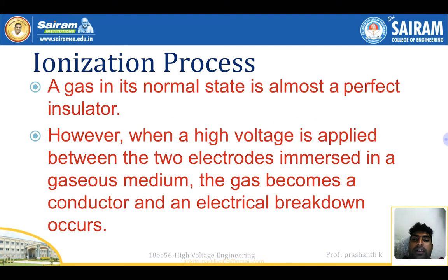Next, the ionization process. The ionization process occurs if the medium is a gas, right? Gas is almost a perfect insulator, everybody knows. However, when a high voltage is applied between two electrodes immersed in a gaseous medium, the gas becomes a conductor and electrical breakdown occurs.